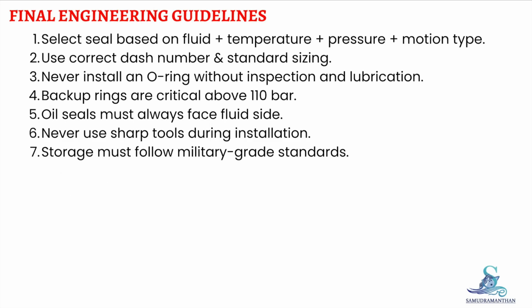Let's talk about some guidelines to be followed. Always select seals based on fluid type, temperature, pressure, and motion. Use the correct dash number and gland dimensions. Inspect and lubricate O-rings before installation. Use backup rings for high-pressure applications. Oil seals must always face the fluid side. Avoid sharp tools during installation. Maintain proper storage and handling to prevent aging.